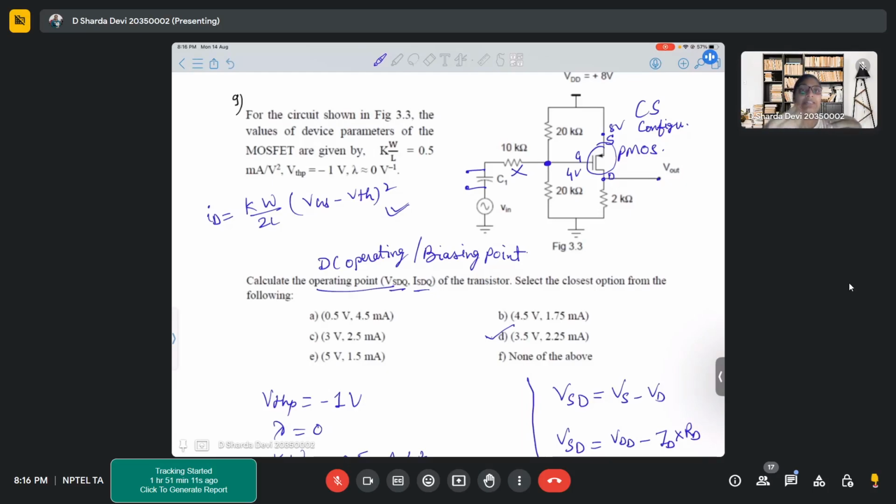Theoretically, while studying the AC condition, we put DCs to ground, and while considering DC condition, we put ACs to ground, to simplify the calculations.